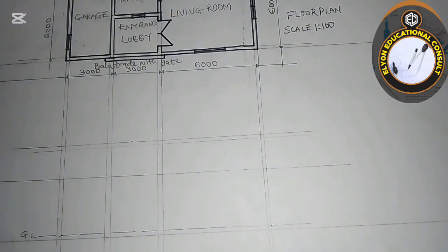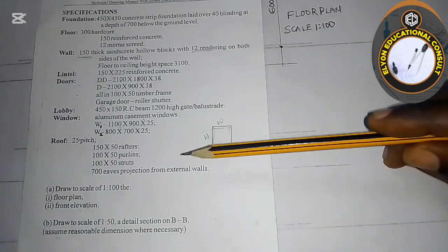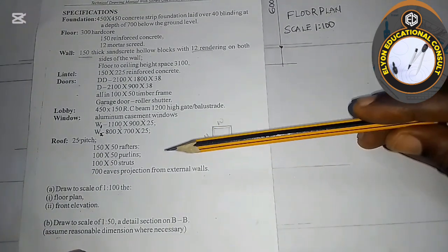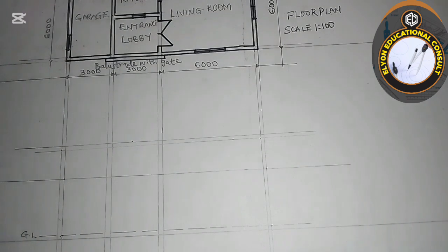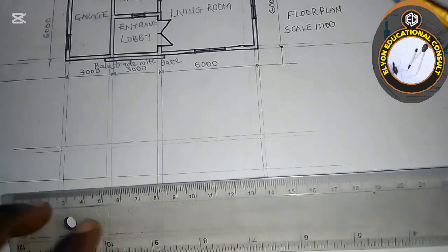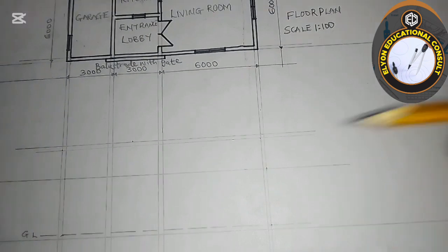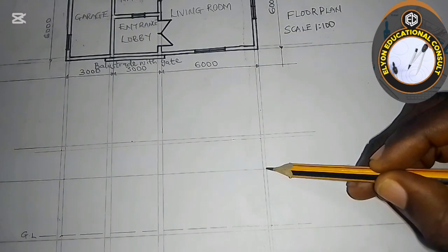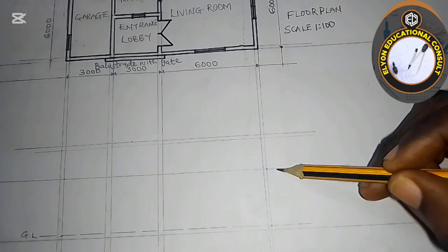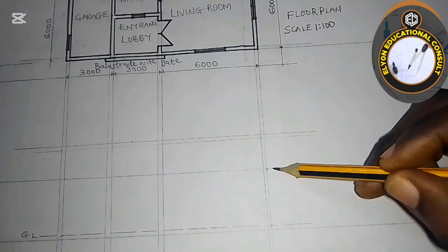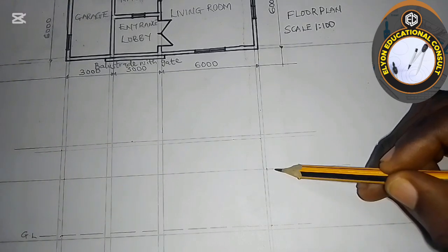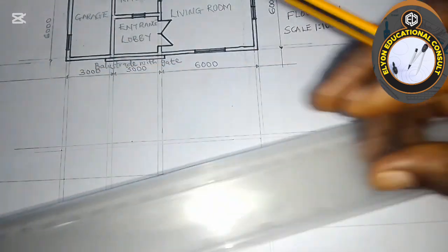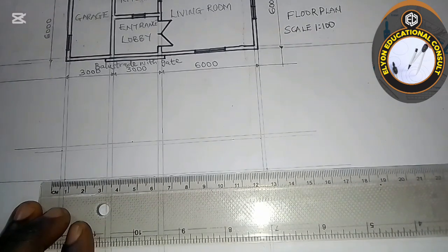Now if you look at the roof, the eave is not given in some questions, the eaves are always given, but since we are not given, I'm going to assume a measurement for that, because we need to show that as well. So I'm going to use 0.5, and the 0.5 should be from this wall here. So the extension, the projection of the roof out like this at both sides is the eave. So I will take that as 0.5.